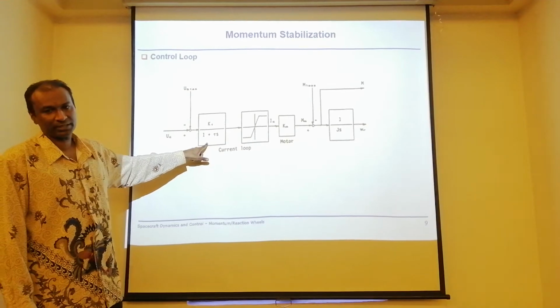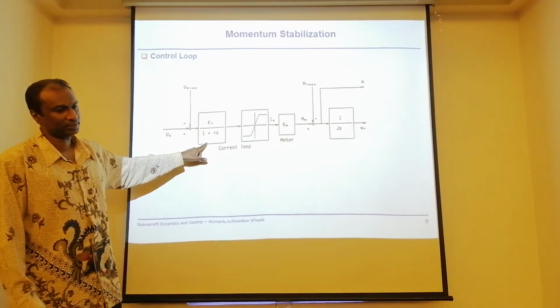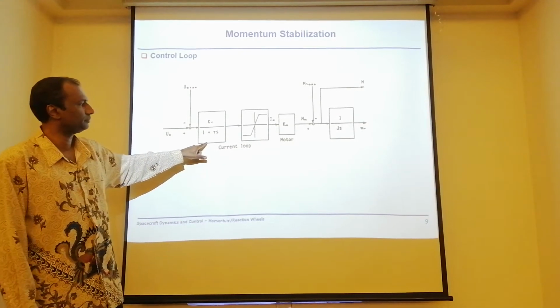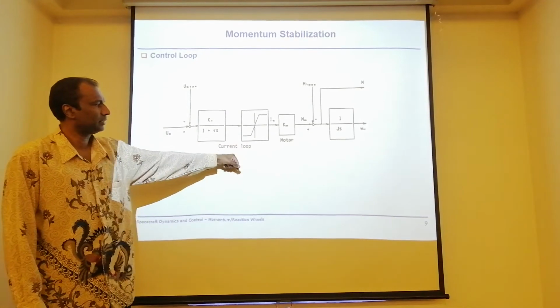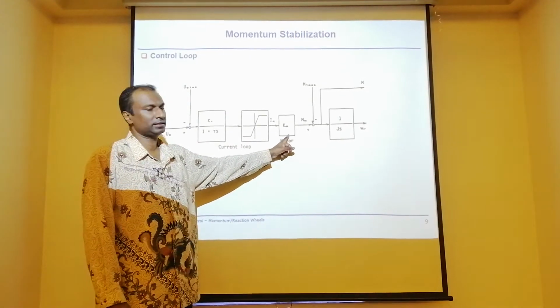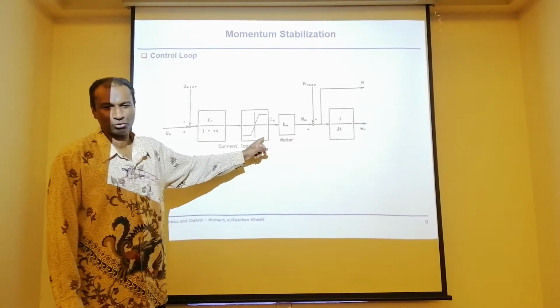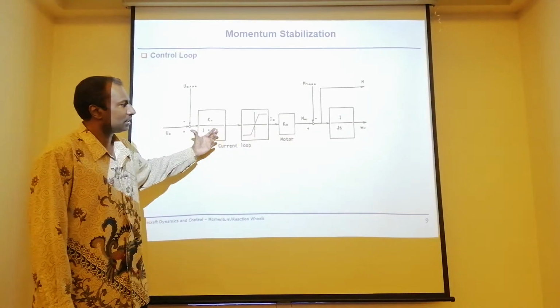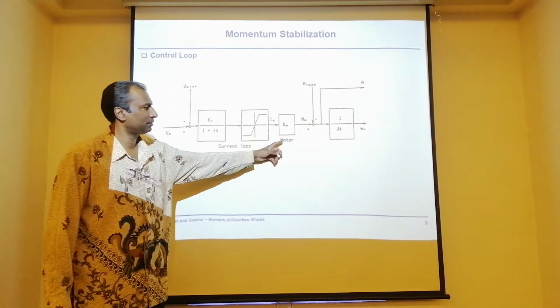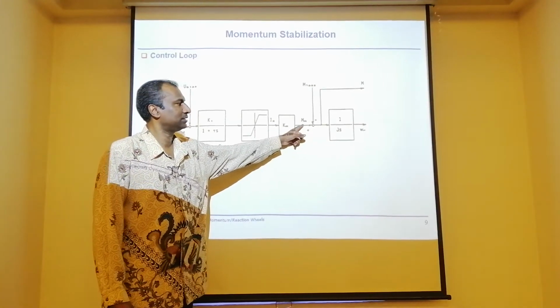Typical, basically, first order. Just a proportional controller. You have current, and this is basically the motor constant that you have. So how much current? This is a typical motor controller. Just to tell you. Then how much current that you inject? That is the amount of actual torque that will be generated.